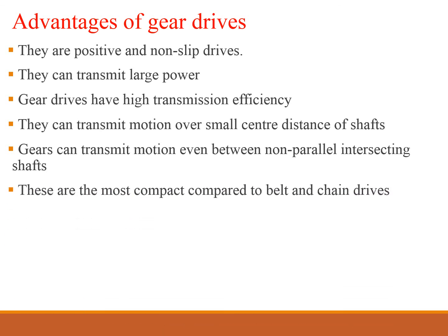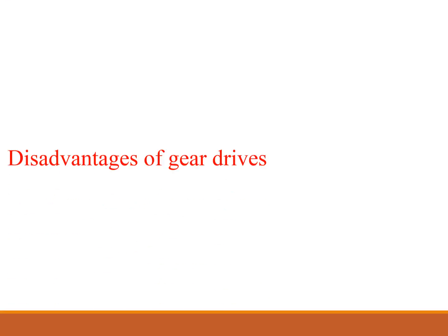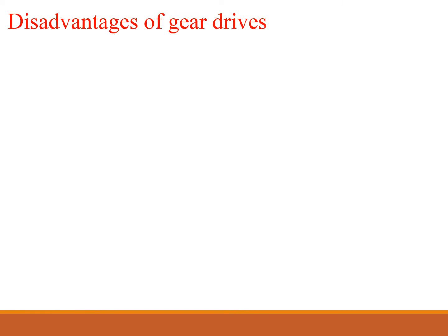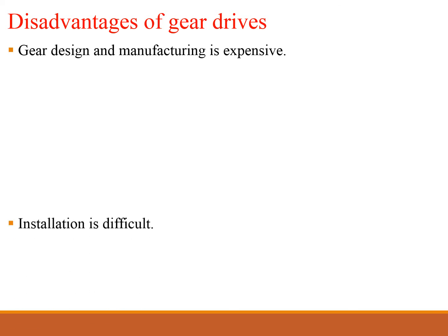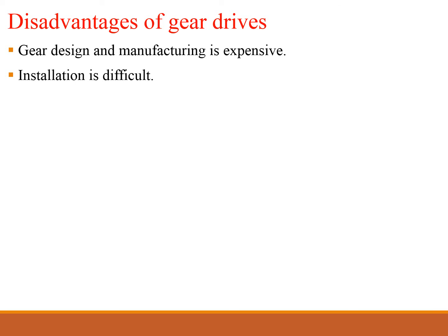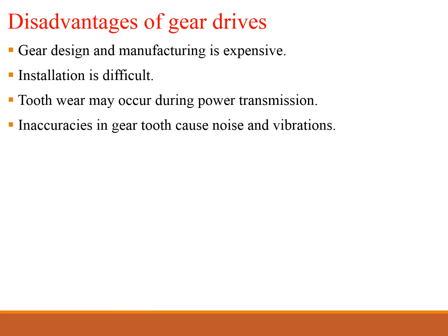These are the most compact compared to belt and chain drives. Disadvantages of gear drive. Gear design and manufacturing is expensive. Installation is difficult. Tooth wear may occur during power transmission. Inaccuracy in gear teeth causes noise and vibration.